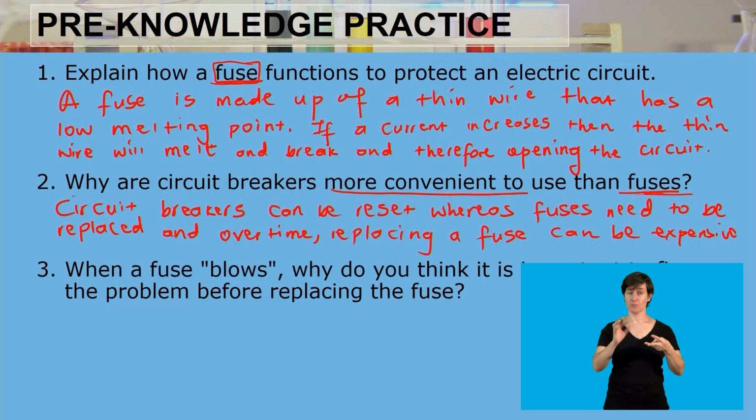Now, question 3 is asking, when a fuse blows, why do you think it is important to fix the problem before replacing the fuse? Now, remember that the fuse is used to protect the electric circuit. So once the fuse is no longer there to protect the electric circuit, then that increase in the current strength is going to damage the entire circuit.